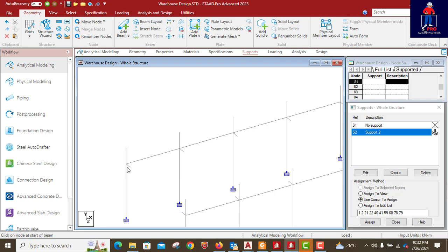cantilever. So okay, I have 650. This beam is 650, and you know my column, I will use HEB 300. So this 650 is supposed to start from this model. Actually, it starts from the middle of that column. So 150 is already buried into this column. So I'm left with 500.